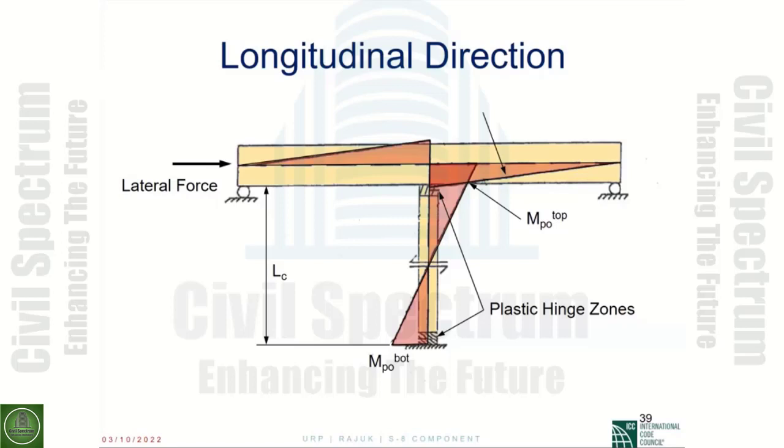Once you have the uplift, the bending moment that we show on the superstructure on the left side cannot really materialize because you cannot restrain the bridge from that, and all the moment of the column would go to the right hand side. So please pay attention to these things.